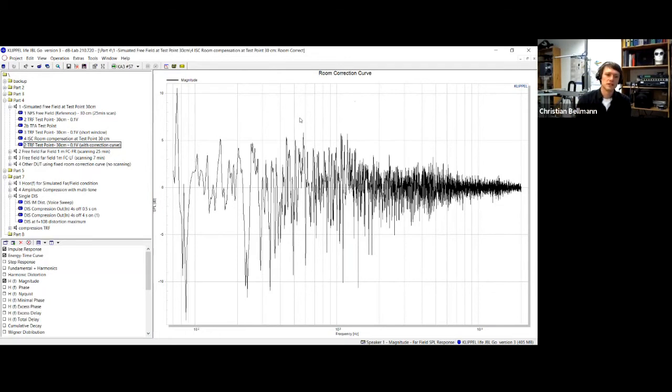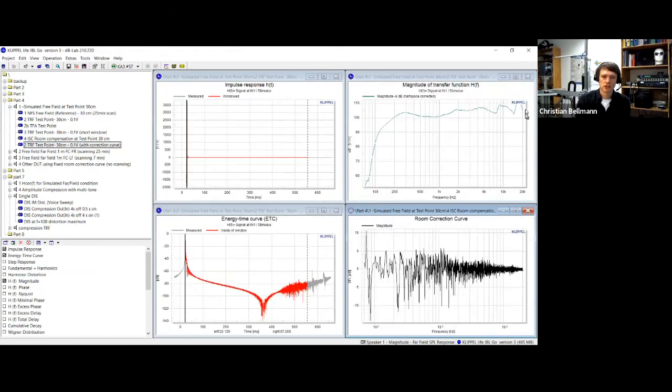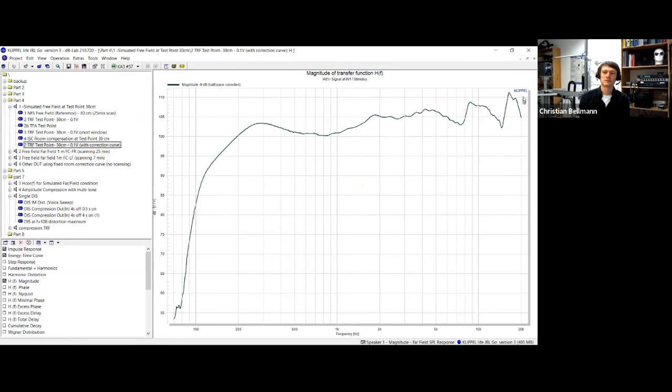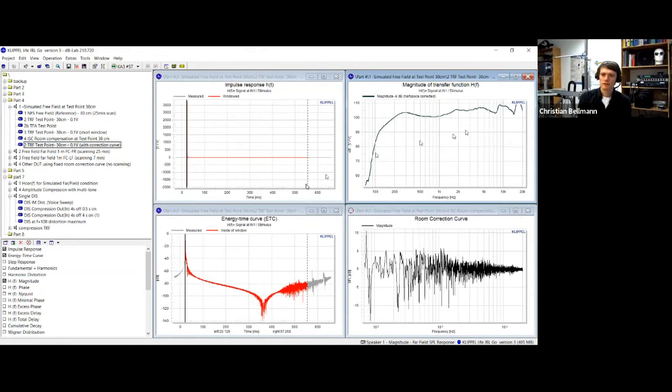But finally, using this, we end up with a clean transfer function. What you see here is what we expect from a loudspeaker, and what the near-field scanner measurement also predicted at this position. But we have to say that at high frequencies we're not using the near-field scanner; we used the original measurement data, windowed.